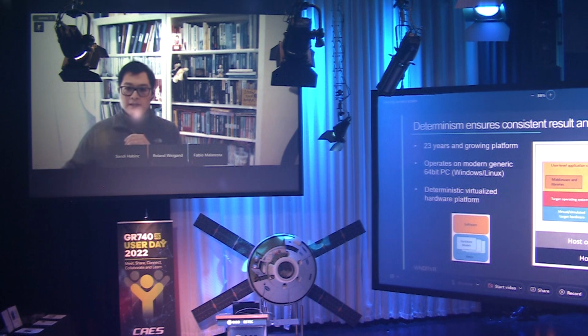So we can imagine that Simics provides this environment to allow us to write and instantiate different hardware models. It's a protective environment that protects all these different hardware models. For example, in the case of GR740, there is the LEON4 processor, the SPI controller, the PCI controller, and the timer itself.